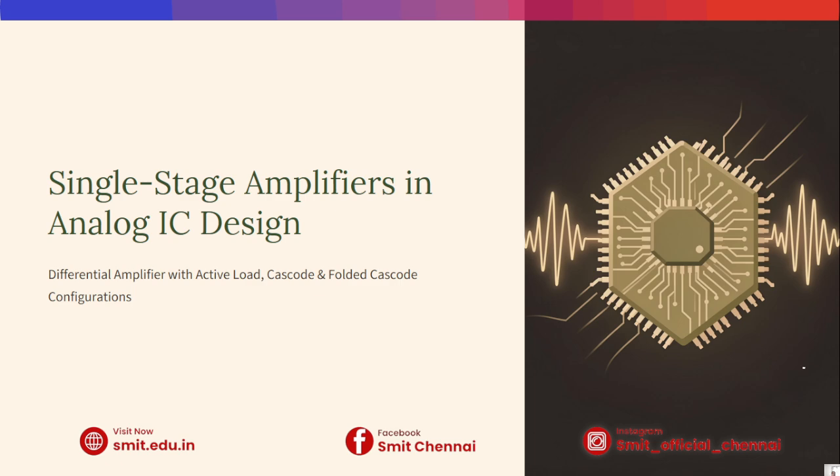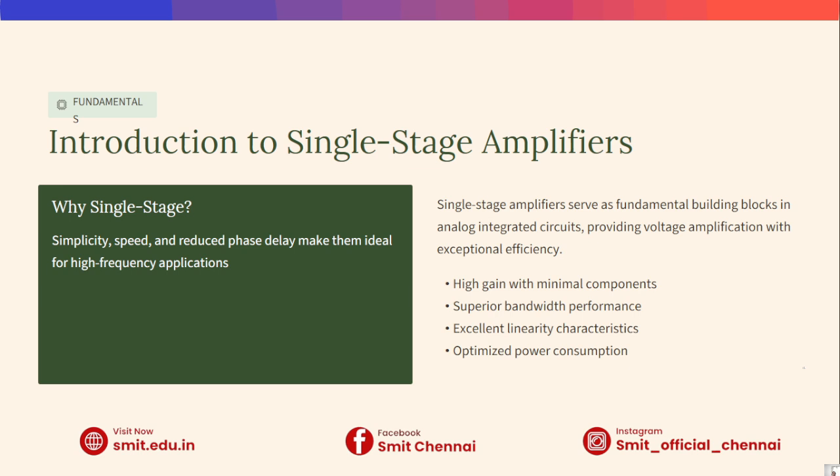In this lecture, we will see about the single stage amplifiers in analog IC design, focusing on differential amplifiers with the active loads, cascode and folded cascode configurations. These are fundamental building blocks in analog circuits, and understanding them is key to designing the high performance ICs.